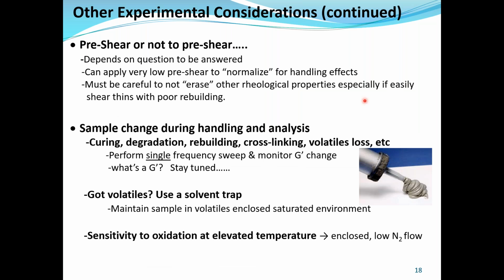Okay, the last set of experimental considerations is to pre-shear or not to pre-shear? That depends on the question to be answered. What I mean by that is in the process of adding a sample to the rheometer, you may be imparting some shear, and that may rheologically change your sample. So you may want to consider pre-shearing your sample, typically in the opposite direction, at very low shear, just to normalize your sample, and then you can begin your assays from there. It gives all the samples the same starting point.